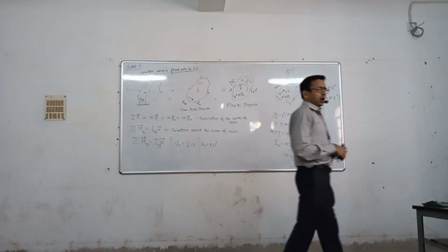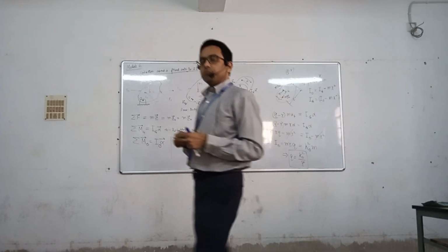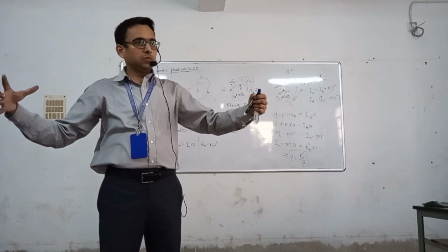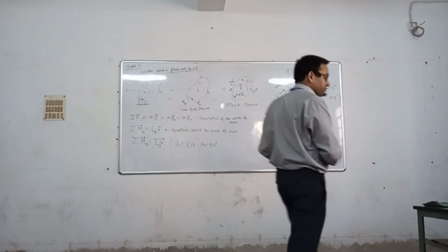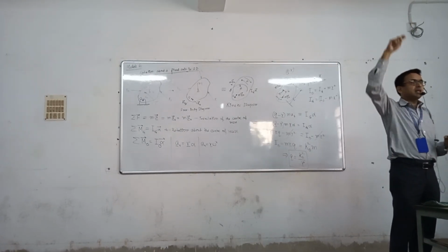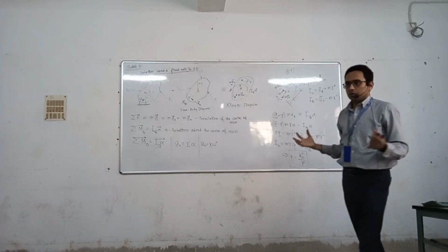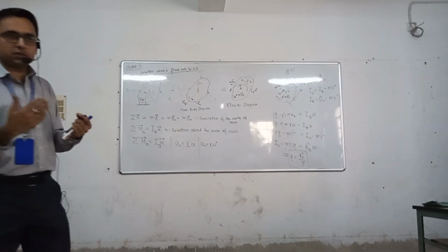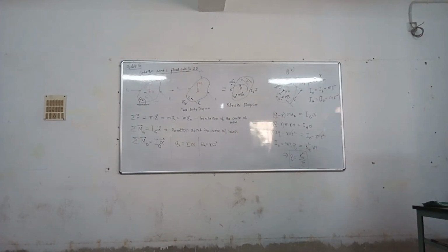Other industrial applications: say, for example, you want to demolish some building with some pendulum. Large pendulums, large bomb pendulums, you have seen, to destroy buildings. Now, from wherever place it is held, if that gets a reaction, then it may be damaged. So if the pendulum has a center of percussion and the load is supplied through the center of percussion, then there will be no tangential load on the bearing.